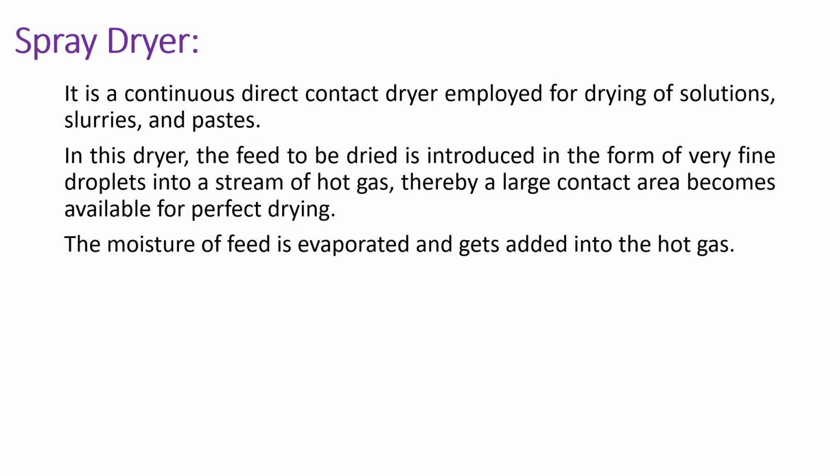So the main principle of spray dryer is that the liquid is broken into tiny droplets, and these tiny droplets have very large surface area, therefore moisture evaporates very quickly, and this gives rapid and efficient drying. So it is more efficient than tray dryer, but it is used only for slurries and pastes, so it is faster than tray dryer.